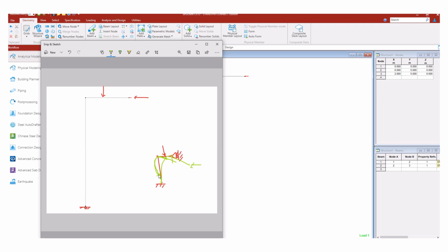So there is a point of counterflexure. That means this joint will try to rotate like this, because this joint cannot move this way, and this joint is fixed. So once it's rotating like this, it will come like this. There is a point of counterflexure somewhere here, and a change in slope, and this will bend until like this. After that it will be a straight piece only, because there is no load, only a horizontal force. There is no vertical force.